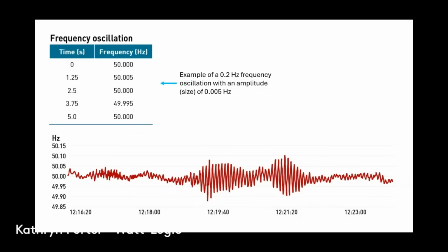So many of these generators were connected to the low voltage distribution network, and the system operator can't see that generation. All it can see is the impact it has on the high voltage transmission system, which is what the system operator manages. And so it looks like a big increase in demand, because the demand was always there on the low voltage grid, but it was being met by local generation. But when that local generation went away, that demand then was sent through to the high voltage grid, and very suddenly REE had a lot more demand to manage than it had expected, because this happened pretty much instantaneously. All of these solar farms just turned off.